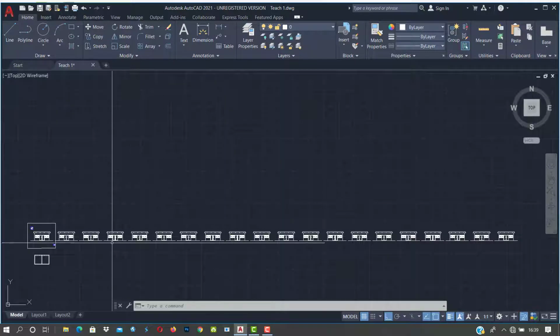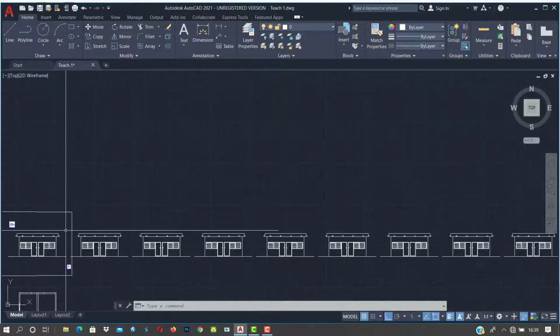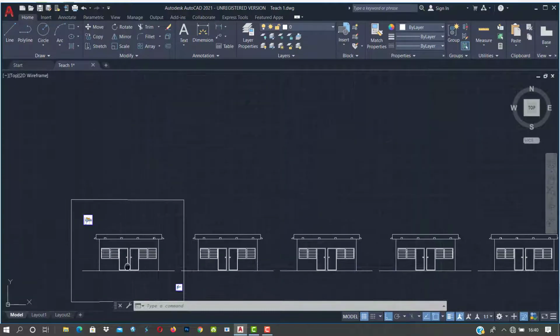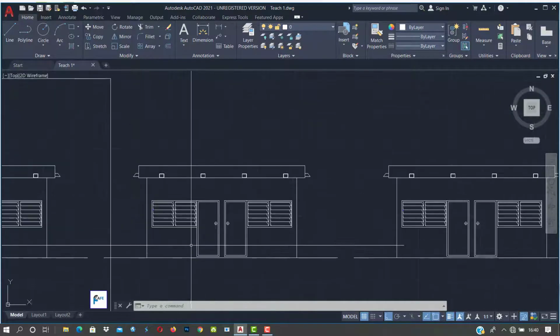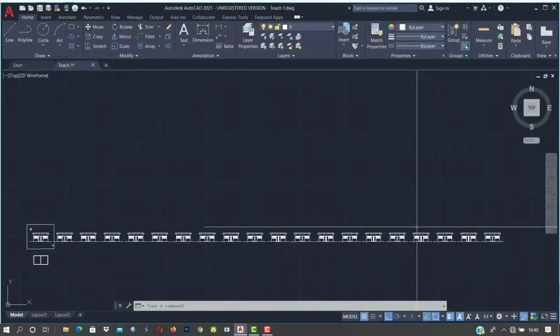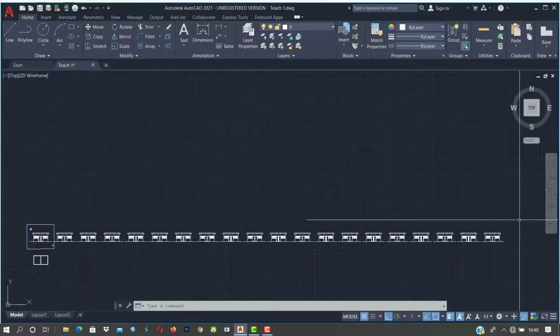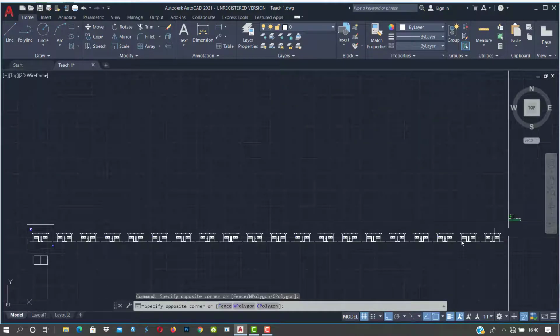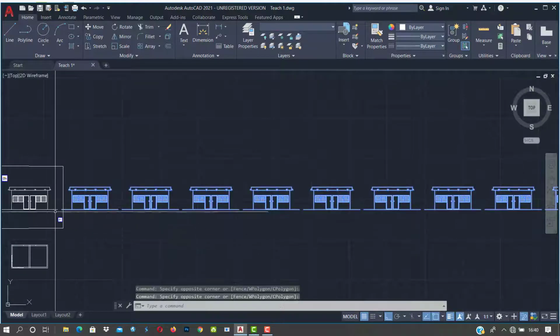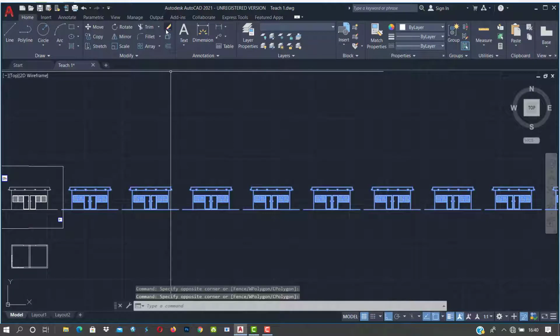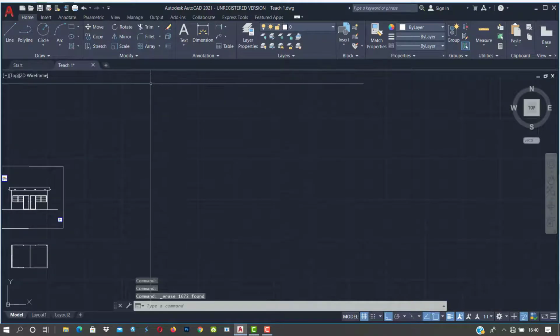For those of you who have seen estate buildings before, most of them look similar. So people normally use the copy array command to prepare their plans and their deviations and all those stuff. So you can either delete them, erase. I hope you remember the erase command. So friends, select, and I'll press my erase command over here, or I'll type erase, any of the one you need.